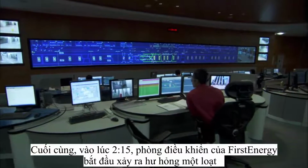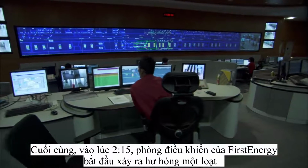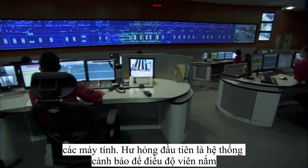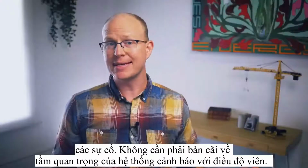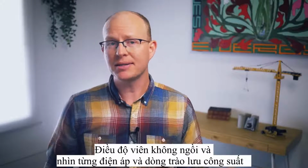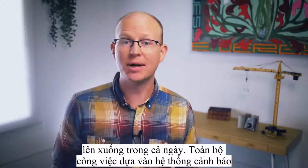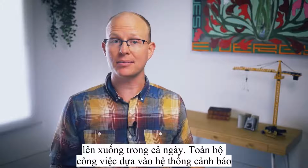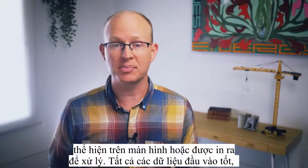Finally, at around 2:15, First Energy's control room started experiencing a series of computer failures. The first thing to go was the alarm system designed to notify operators when equipment had problems. This probably doesn't need to be said, but alarms are important in grid operations. People in the control room don't just sit and watch the voltage and current levels as they move up and down over the course of a day. Their entire workflow is based on alarms that show up as on-screen or printed notifications so they can respond.